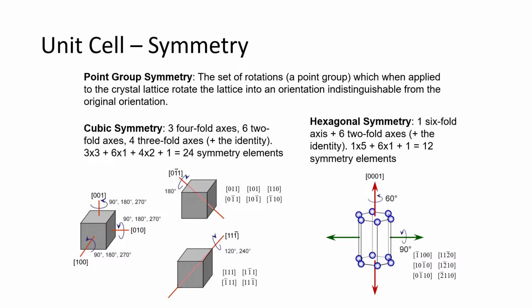And you just have to know about those because mathematically, as we start to calculate textures and preferred orientations, if you get one that's rotated with respect to some specific direction, and then you get another one that's 90 degrees rotated about 100, and you're plotting those and calculating them separate, even though they're the exact same thing, then you're reducing the actual preferred orientation in your material. So you have to take account of all the symmetries. Okay.